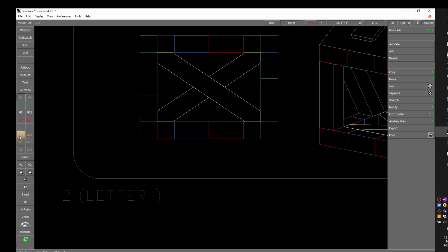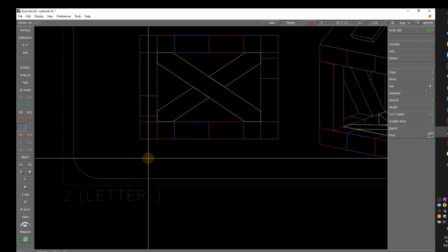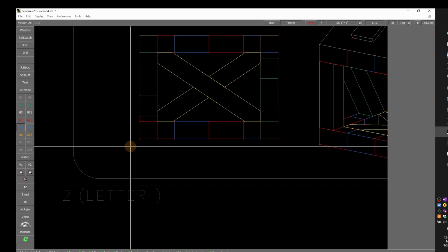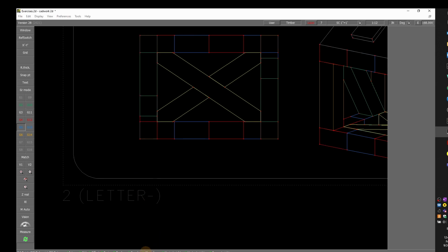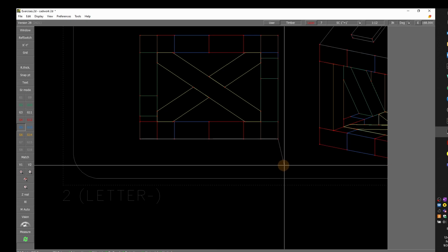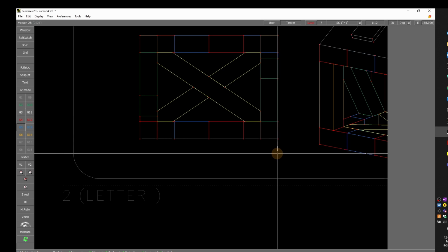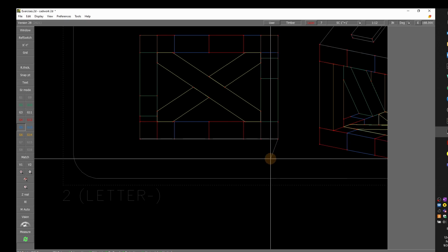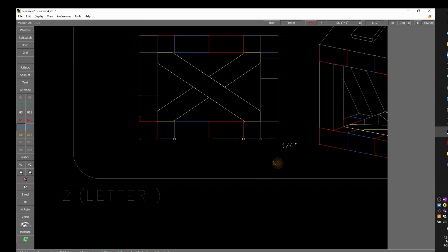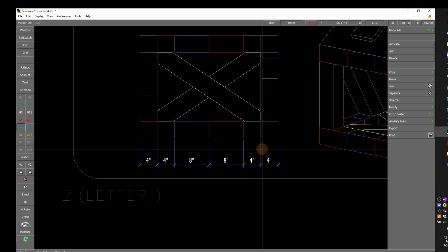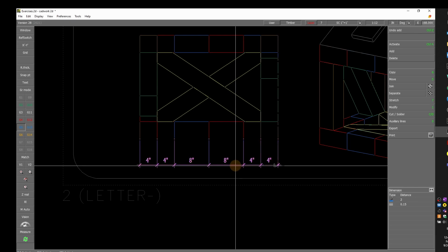So here I'm going to set it to G5, and then I'm going to press H for horizontal. Then I'm going to pick, and then I'm going to press L for a long line, and then I'm going to pick 2 points. It could be like a polyline as well, it would work. But here I need a string that goes from the bottom left to the bottom right. I right click and then I can place the string.